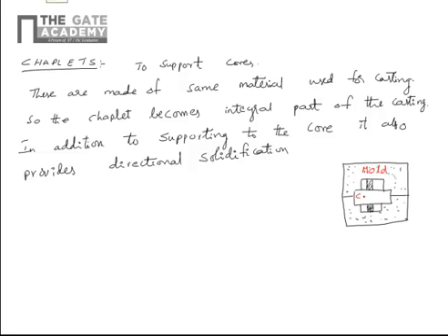And this one is the core, which is made of sand. And these are called chaplets to support the core. The empty space is the casting cavity. You can use multiple chaplets to support cores. So directional solidification is solidification towards the riser, which we will discuss.